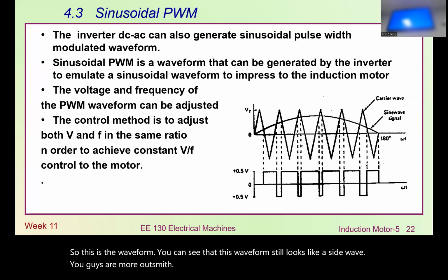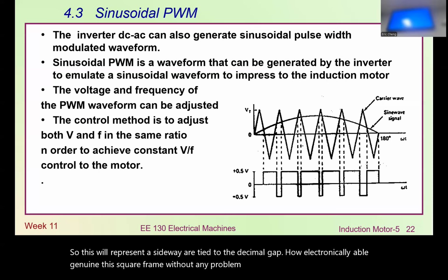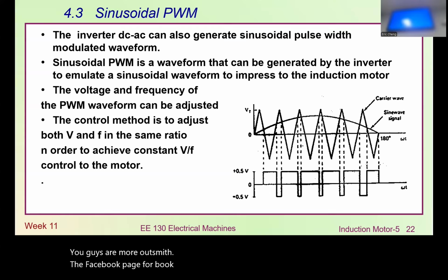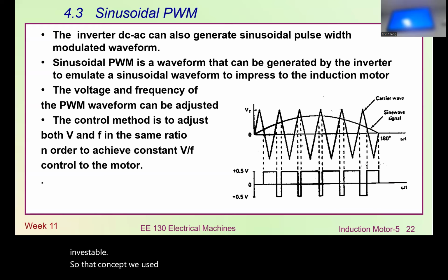Electronically we are able to generate this square wave without any problem, only turning on and off. But this voltage, from the volt-second point of view, from the power point of view, is equal to the same fundamental level. So that's why we use this method to energize the induction motor. The concept behind it we call sinusoidal PWM. Sinusoidal PWM, we don't cover the formulation here.